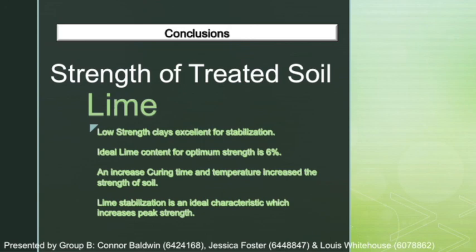It has been identified that the ideal lime content to be added to a reactive soil in order to achieve optimum strength is 6%. Furthermore, as the curing time and temperature of the treated soil increase after the introduction of lime, so does the strength of the soil. The relationship between these parameters and the strength increase of soil is an important concept to model to ensure consistent predictions in a wide variety of lime stabilisation applications.